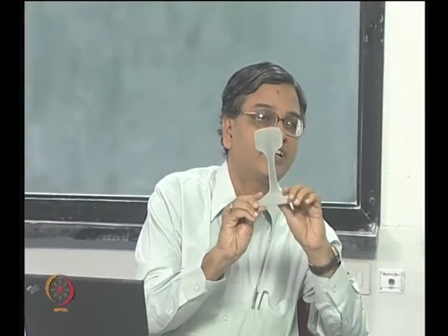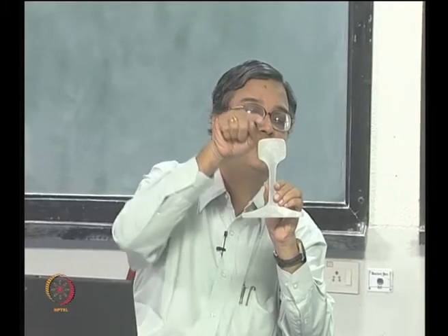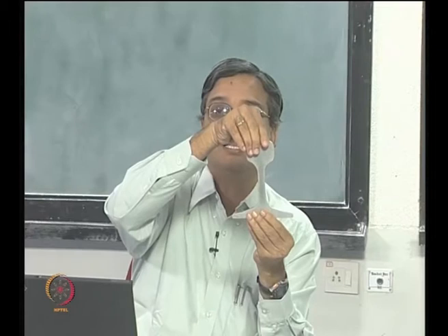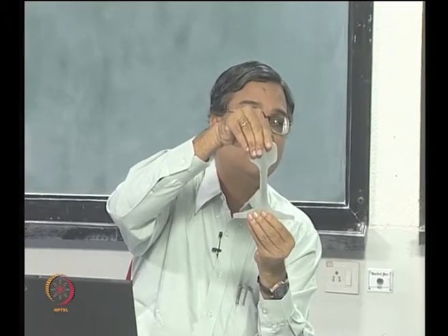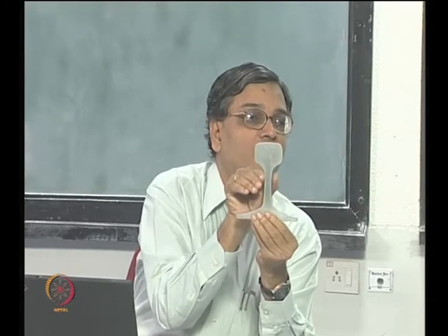And what is seen when you go to how this is used in design? If you see a rail cross section, you do not have a square block, because you know that it is subjected to load on the top face, and it is essentially transmitting a bending load. Since the inner core is not participating, you have removed the material.